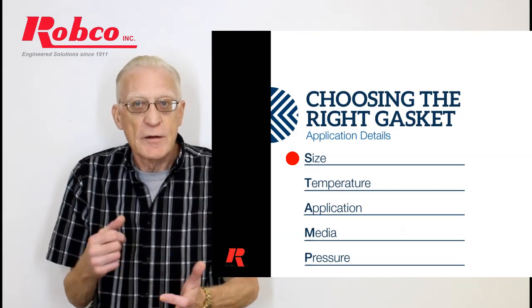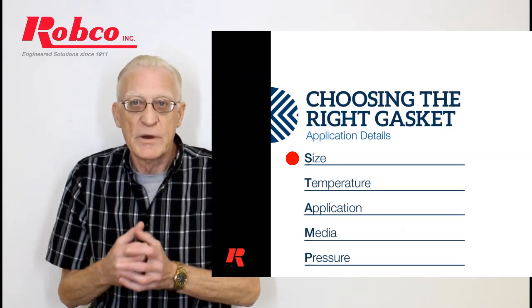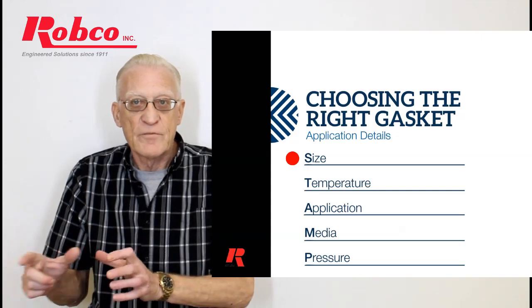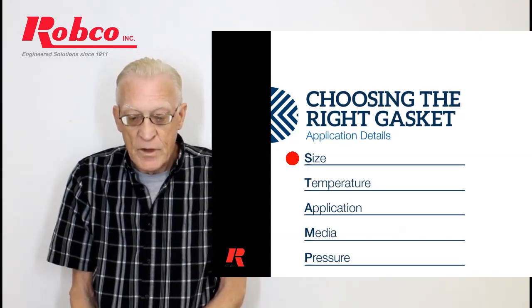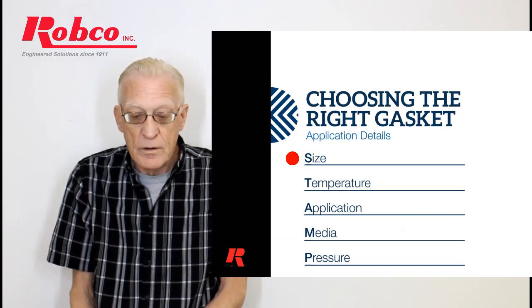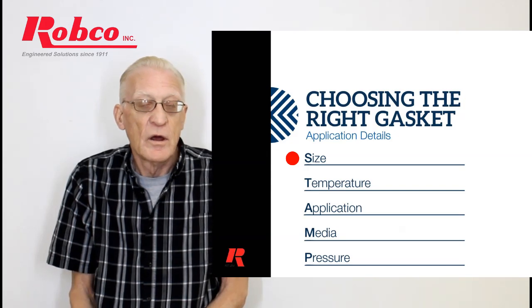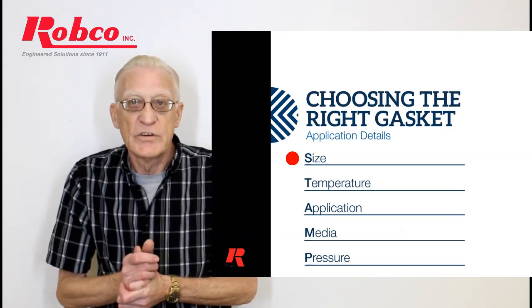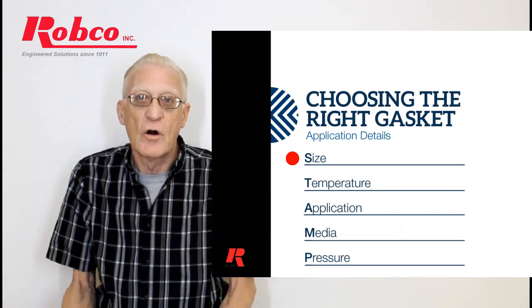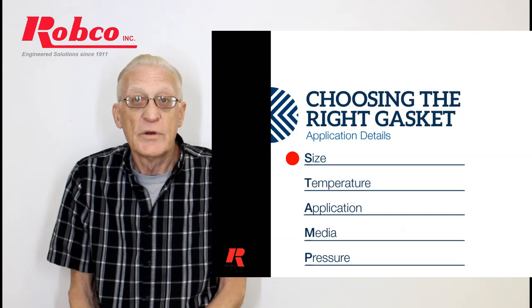But they are designed by engineers over the last 100 years to be this for that flange, this for that flange, and it doesn't change. So for size, you need to know the class of the pipe, 150, 300 pound. Again, go back to the ASME B16.5, which regiments all the gasket dimensions and so on. It'll tell you exactly how big that gasket is.